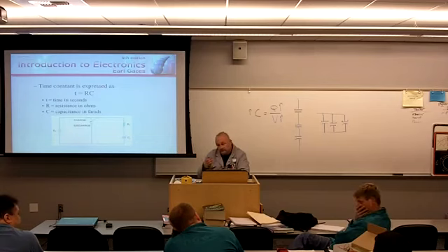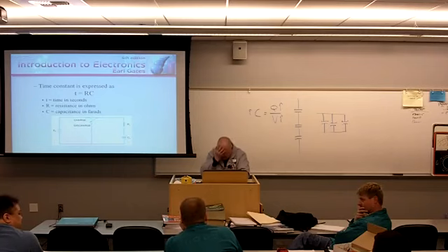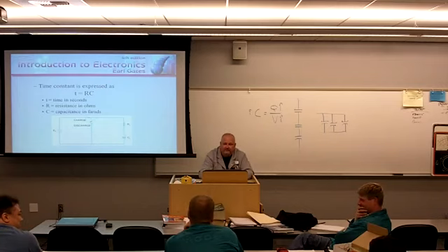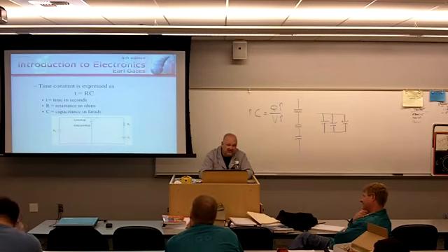Because the 6th would be 99.3%? Because on the 5th time constant it would be 99.3%, right? After 5 time constants, we call it even. But the books that you read do sometimes have a 6th time constant. Well, yeah. If you're dealing with real high power stuff, that could be a difference. If it was high power and a high voltage, it could be the difference of a couple volts, that small percentage. But generally, it's accepted 5 time constants. Every exam you take here, it'll be 5 time constants.